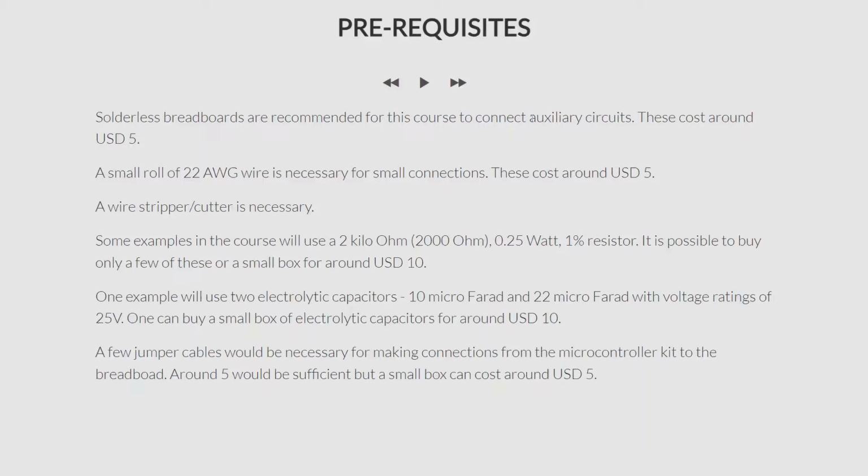power electronic applications because you can use these pins to control, number 1, LEDs for display, like you want to show to the user that there is an overcurrent fault or an undervoltage fault, or sometimes even you want to use it for control, like you want to use it to turn off a relay, which in turn controls a contactor, right? So you want to disconnect your converter from the grid. Then you can use these GPIOs for that purpose. And this way, using these breadboards, we will play around with some small circuits. The cost of these solderless breadboards is around $5, right?